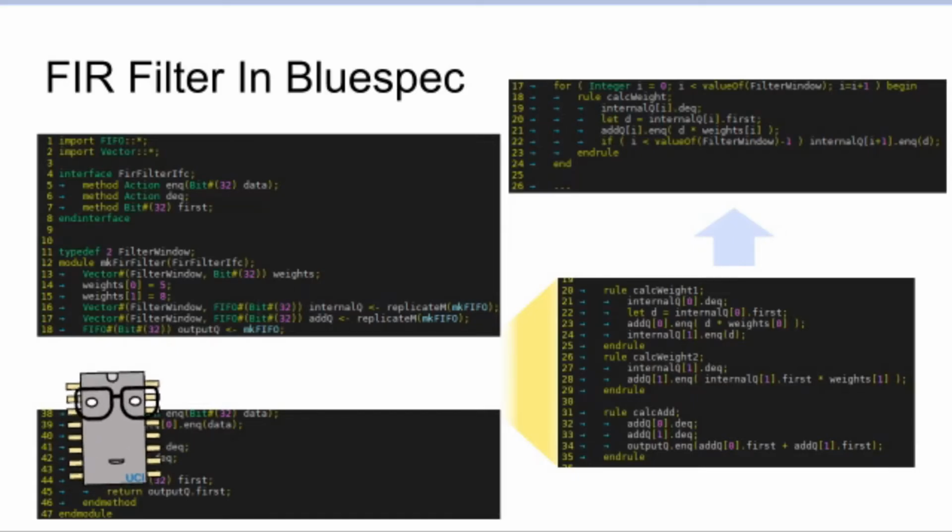Right. So last week, we talked about finite impulse response filters in BlueSpec, not just in BlueSpec, in general, how to implement this in hardware. Because, like you mentioned last lecture, if we try to implement something like this in a filter, in a kind of like how we do it in software by having a two-layer nested for loop, that will be very, very bad for performance, partially because the clock frequency of FPGAs is relatively low.